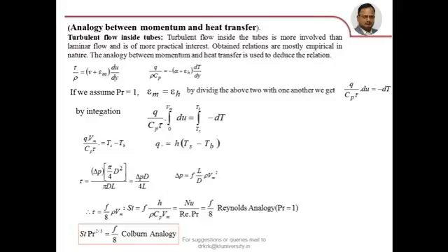Because even internal flow is a forced convective flow, in this case also the Nusselt number is a function of both Reynolds number and Prandtl number. And we have already seen through Prandtl that in the case of turbulent flow, the thermal boundary layer thickness and hydrodynamic boundary layer thickness become the same, or the momentum diffusivity and thermal diffusivity become the same.